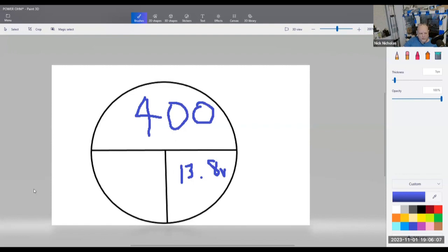I've got to grab a calculator to do this. 400, you can't see it, I'm sorry. That's 29.98 amps. So I would buy a minimum of a 40 amp power supply, but you can get by with a 30. And 29.8 is squeaking it. I'd probably buy a 50.